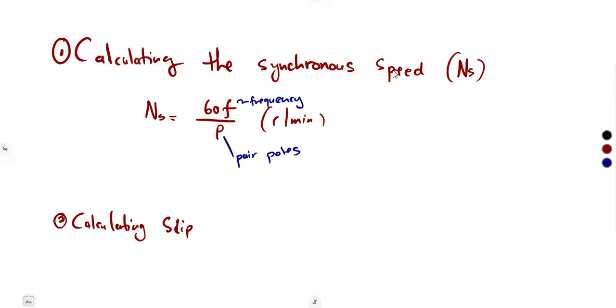So the difference gives us now a ratio which is going to be calculated as a percentage, or it can be calculated as per unit slip. All right. So slip is just gonna use letter S, right? So S per unit slip. Remember our ratio, NS, our synchronous speed, minus N, which is our actual speed. So we're gonna use N to represent the actual speed.